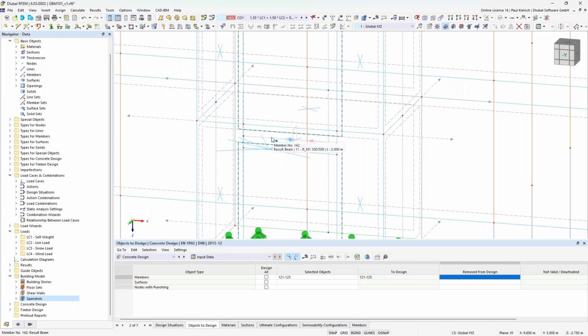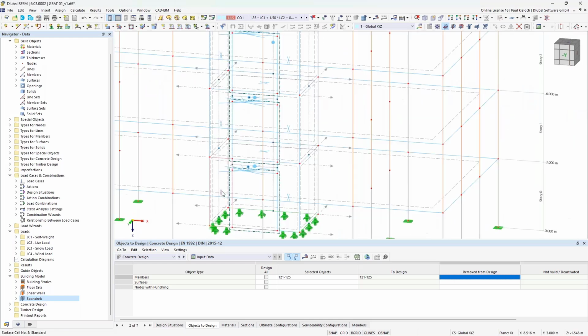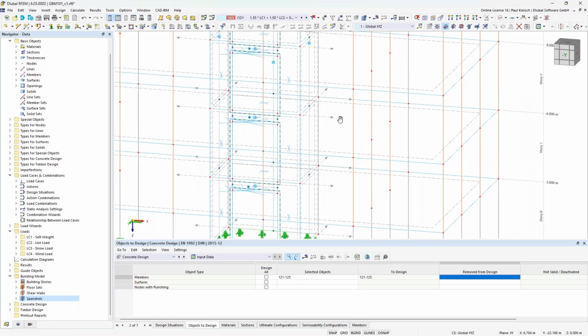So I've generated these result beams here by clicking on the cell. Of course, like I said before, you can use the regular slabs, for example, to generate a deep beam by using this object spandrel, or you can also combine multiple cells by clicking multiple cells to generate a larger spandrel. But in our today's example, I have just used the cells upon the openings.